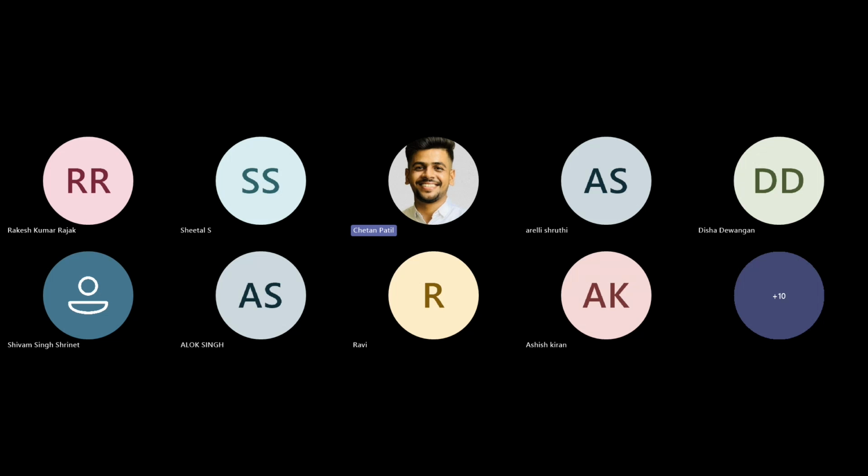Okay, so time step. Time step is one thing that we usually use whenever we want to divide the load that we are applying. If I'm applying a load of, consider, 100 Newton on my geometry, that load is usually considered to be applied from 0 to 1 second. You can decide whatever end time you want; it depends on you what end time you will use for your simulation.